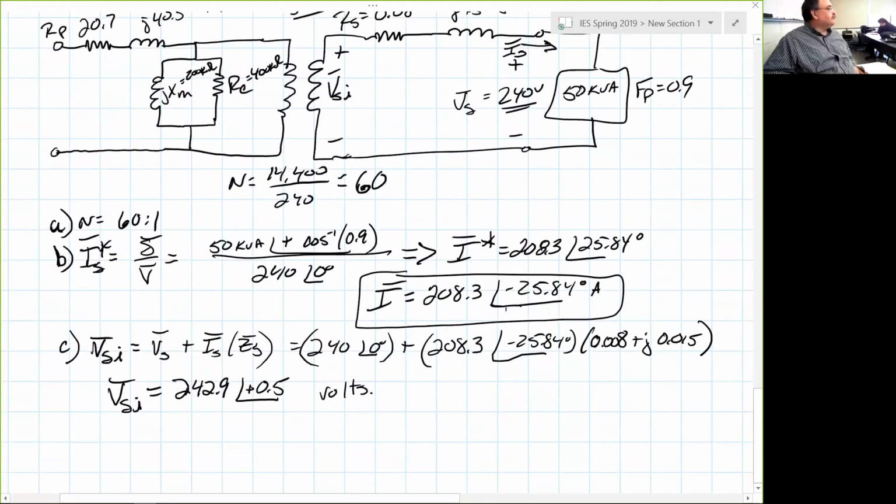Taylor? What is the angle up there? Is that the 50 kVA? Yes, right here. We're calculating what theta is on the VA. It's the inverse cosine of the power factor. See how I did that? I don't know if you've learned that trick yet, but on your Inspires you can plug it in that way. And it says it's a lagging power factor. That's where you have to remember that inductive VARs are positive, so the angle on the VA has to be positive, so that we get a lagging current. Get it?